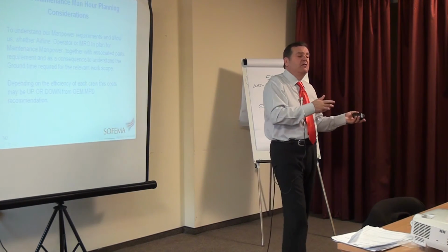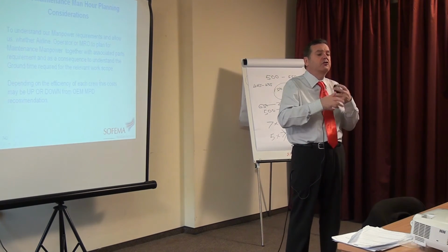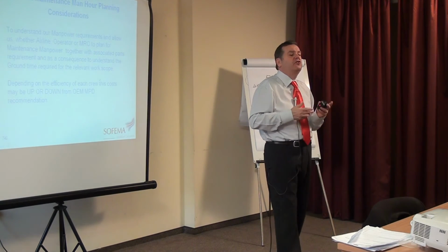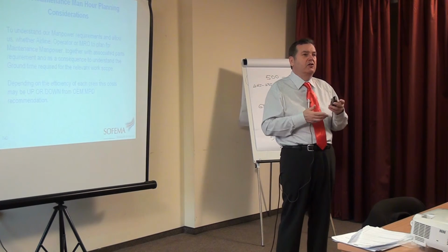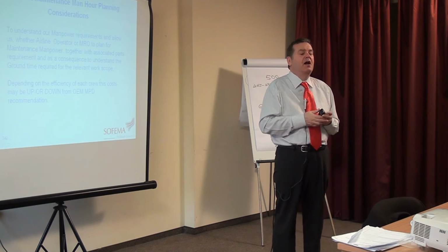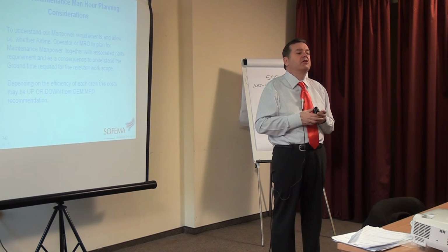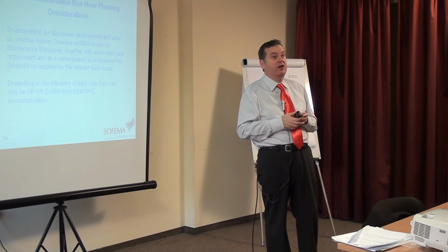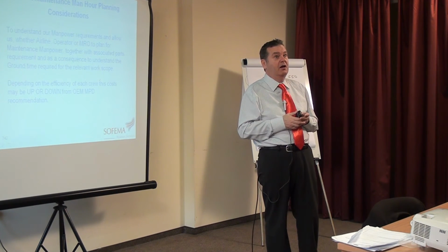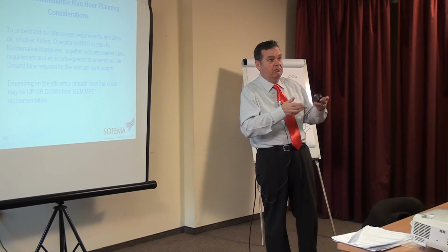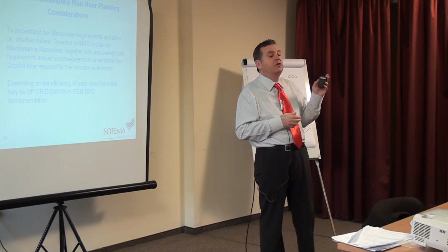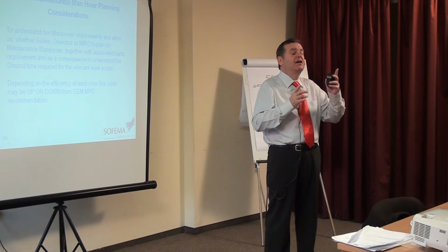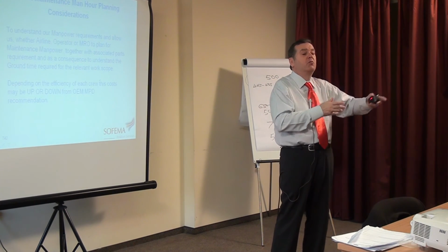And going back to what I was saying earlier about costings, you want a C check and you say, how much will you do a C check for? And if I say to you, based on a 500-hour C check, I'm going to charge you £2,000, plus hours, 2,800 hours, for a 500-hour C-check, you'll say, I'll let you know. And I'll say, how are you getting on? You say, well, I've got a guy who is going to charge me 1,000 hours for this C-check, because he can do it in 2 hours per 1 hour of the MPD.